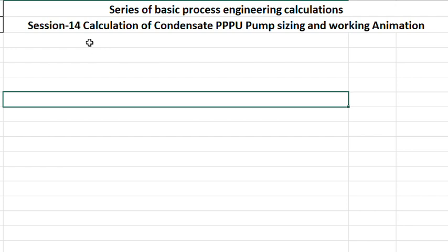Without a proper recovery mechanism, we have to recover that condensate to avoid energy losses and, in order to keep energy requirements to a minimum, it is important that condensate is handled efficiently and the energy from the condensate is recovered and utilized for heating, or in the boiler feed water tank as preheating.